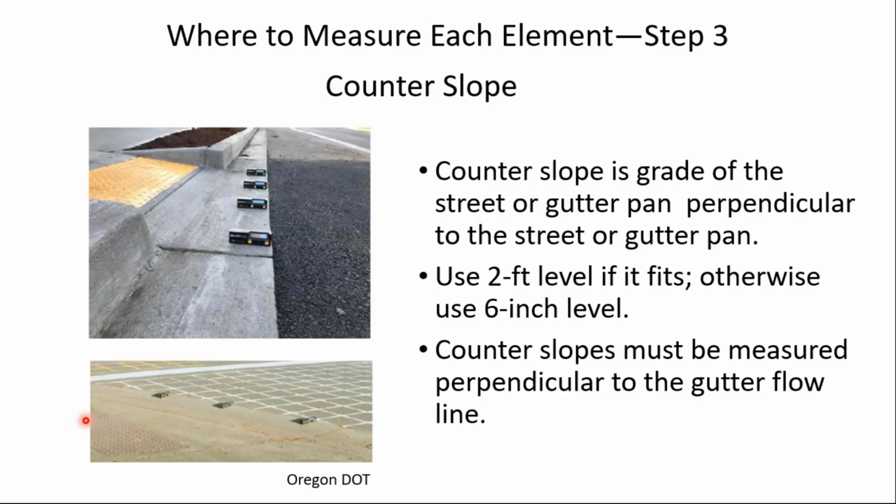They said the 8.33 and 2.1 values are from PROWAG. ODOT requires 7.69 and 1.56 to build in a construction tolerance. Okay, so that's consistent with what I've been talking about. Maybe different values than I mentioned, but yeah, that's good to know. Thanks.